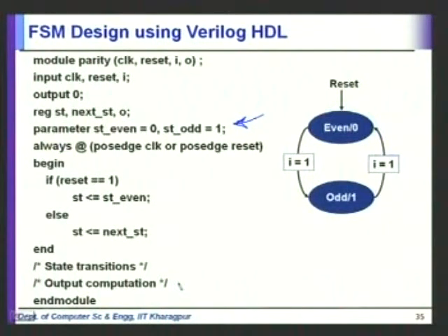So why are we here? I mean, here only one statement is executed. So what is the need of non-blocking? Because we want to take the steady state value of next state. Remember that there are several concurrent always blocks, and they can get executed in any order. I don't want the changed value of next state to be assigned here. I want the stable value of next state from the previous simulation cycle to be assigned here.